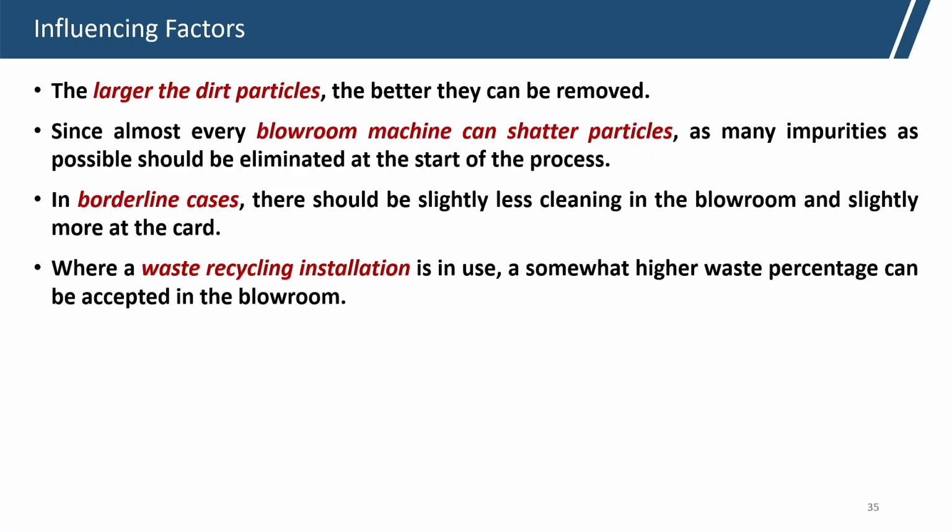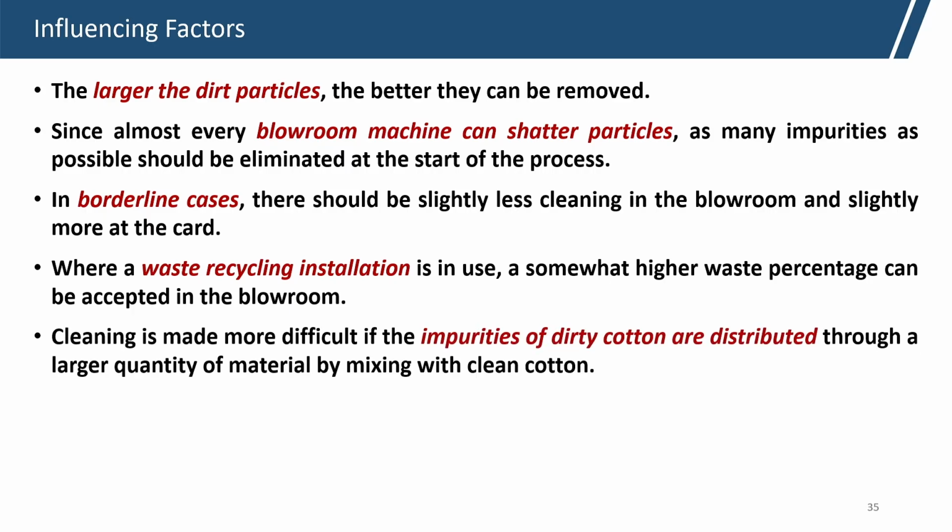Where a waste recycling system is installed and in use, a somewhat higher waste percentage can be accepted in the blow room, because if in the blow room we have a higher percentage of waste, that means some good fibers are coming out, but waste recycling will recycle this fiber. Okay. So, that is why it is acceptable.